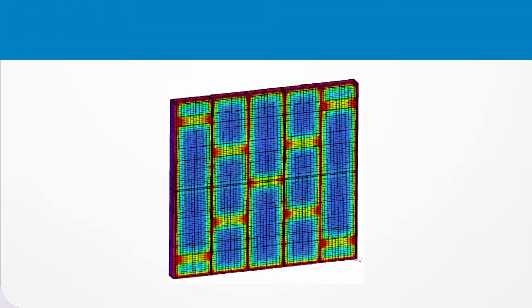Let's use as an example a simple exterior wall consisting of thermal insulation located between vertical steel studs and horizontal steel blocking. If we look at this wall with an infrared camera in winter, from the outside looking in, the space between the studs is blue. This indicates that where there is insulation, there is less heat loss, whereas near the studs, color becomes yellow or red.